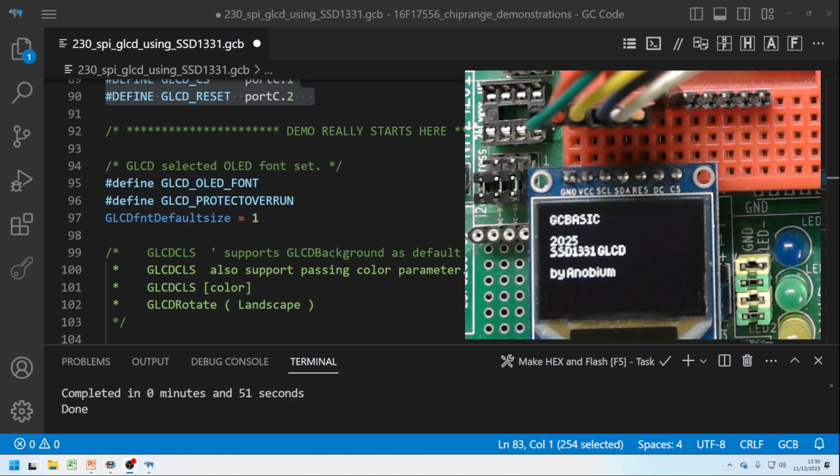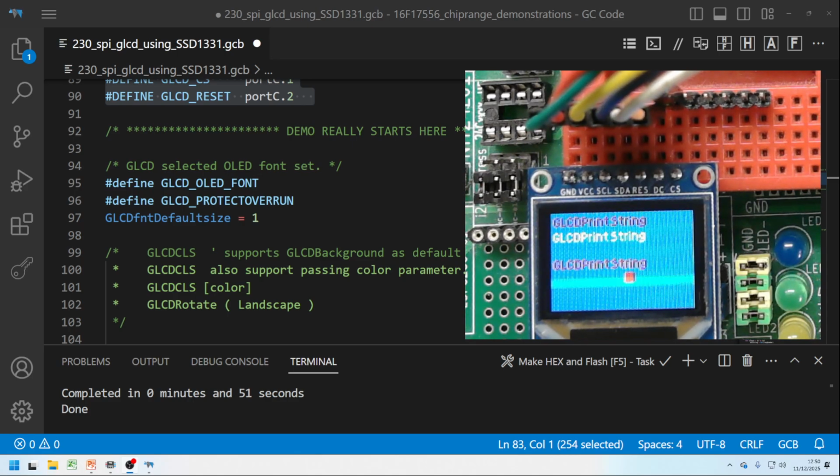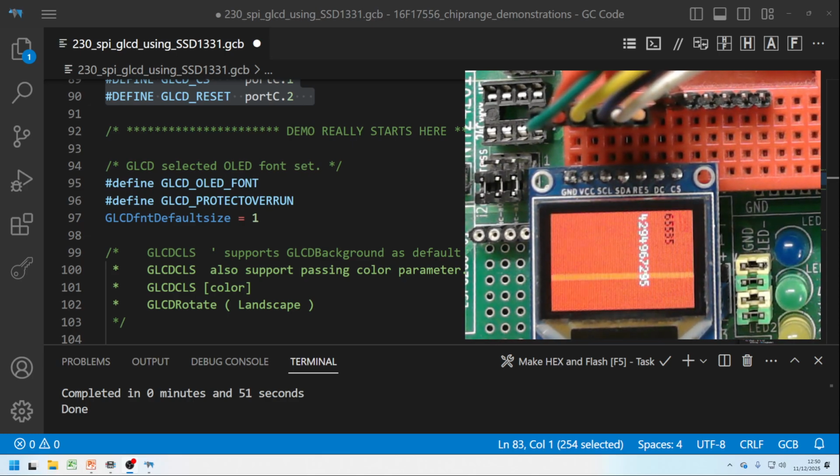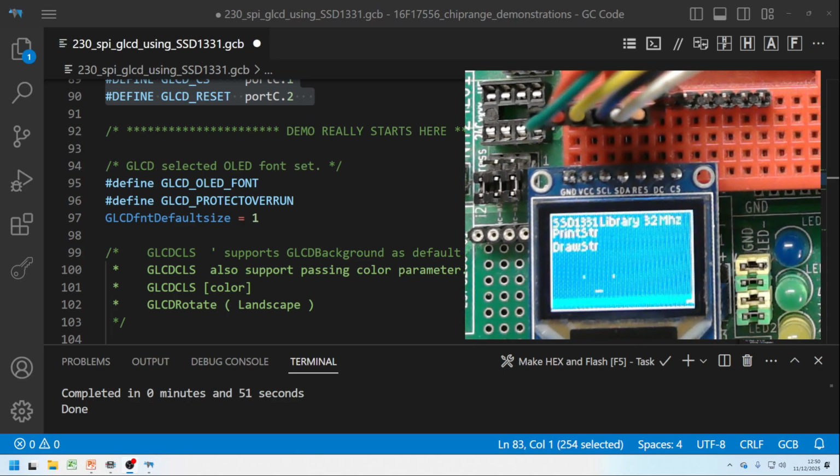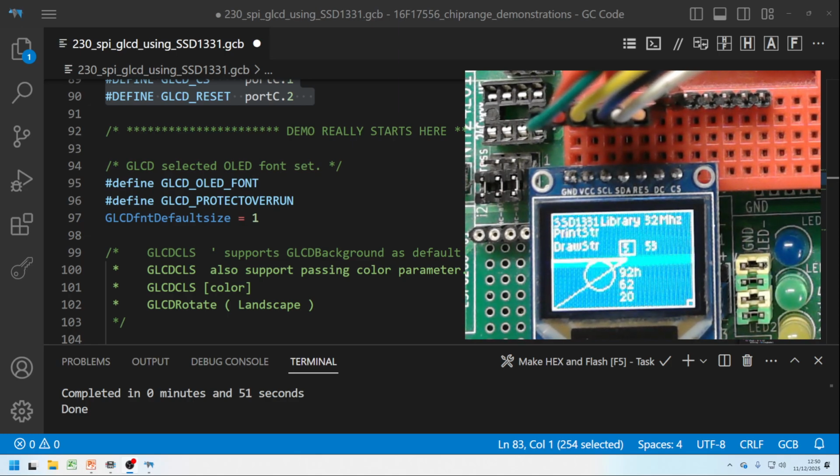Put some text on the screen. Therefore, the SPI is working. We know the data lines are right. It said blue, it's gone blue. It did say red, by the way, and I can't see that flicker on this display here. Long numbers, big numbers, circles, squares, etc., etc. We've got SPI working. In your mind's eye, it's updating that about every second.